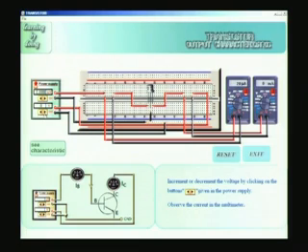Now, let me keep increasing the VCC, and as I increase, please observe what happens to the IC. You would find IC keeps on increasing. The moment I come to 2.5, it is now 4 milliamperes. Beyond that, you find it continues to be 4 milliamperes. It has already reached the saturation value, and it is now 4 milliamperes for all the different voltages that I apply at the VCE voltage.